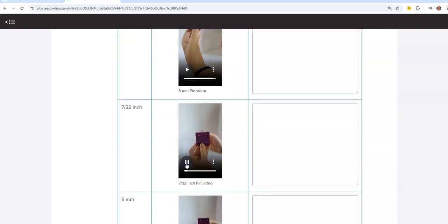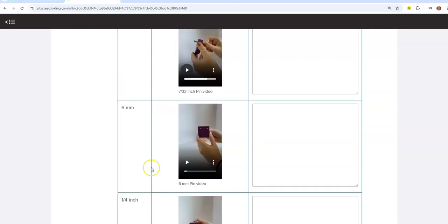Now for this one right here, if you have to put any kind of a struggle through as you turn, this one turns as well. They're trying to say that one's a 7/32 inch. That's a clearance fit as well. Now let's just take a look. Let's see here, 6 millimeters. This can give us some good data for up above too.